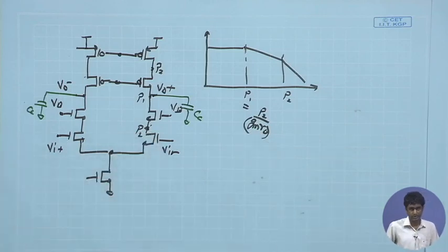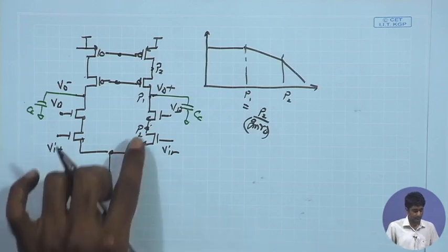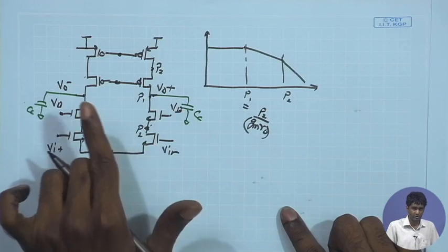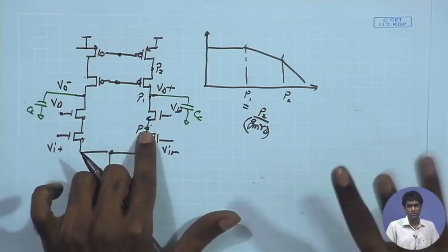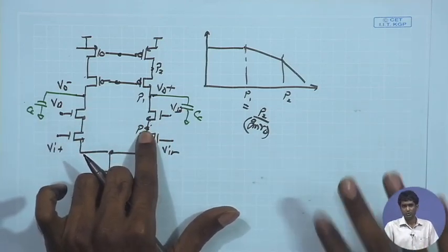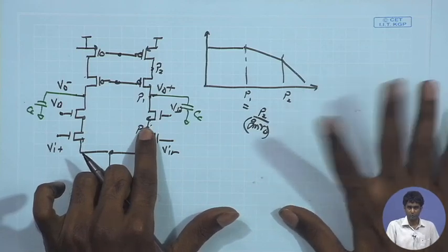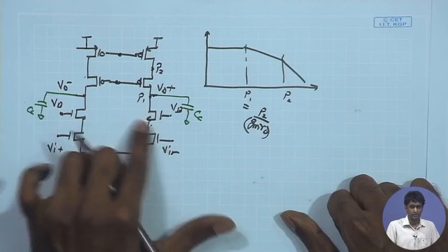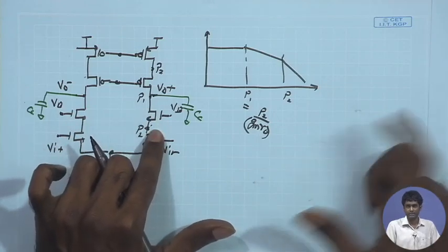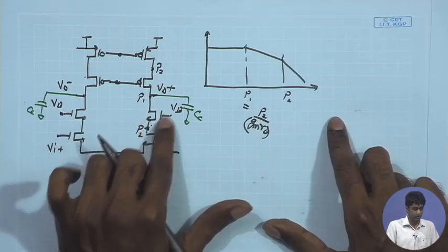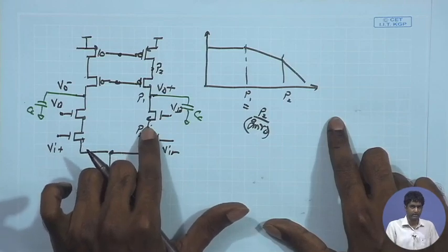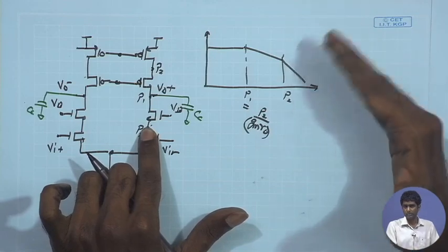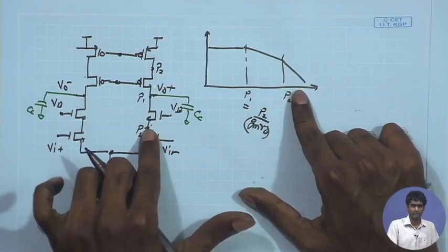If I look at 180 nanometer technology, for example, a 1 micrometer width device, 1 micrometer channel length, may provide you total parasitic capacitance close to, say, a few femto, 1 femto around. Even if you are using larger devices, say few tens of micro, the overall parasitic capacitance over here can be close to few tens of femto to 100 femto. It will not be more than that, close to that range. So a small fraction of picofarad.